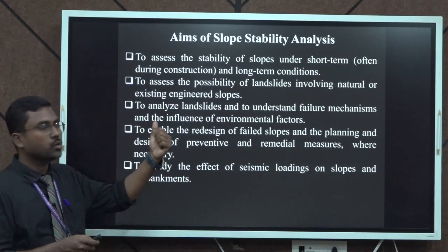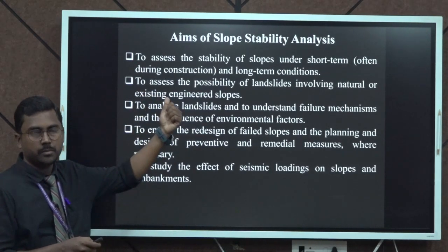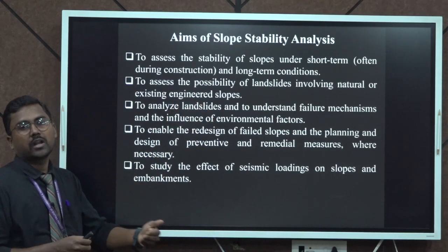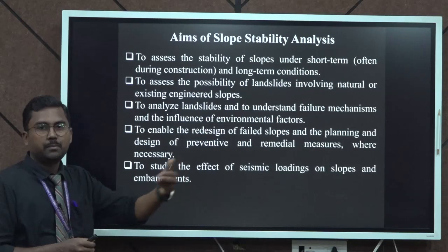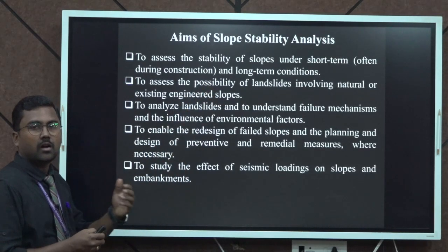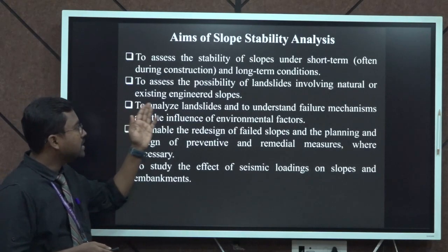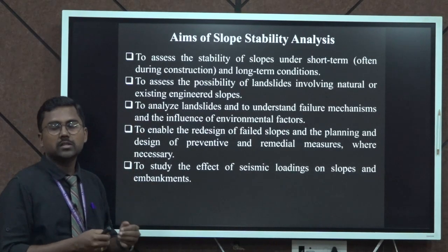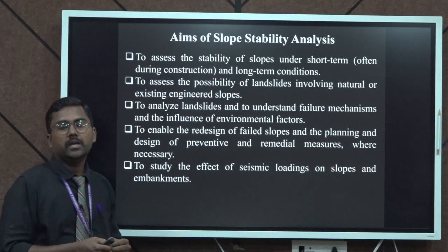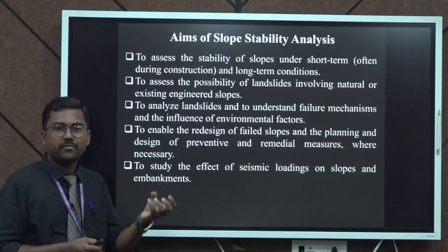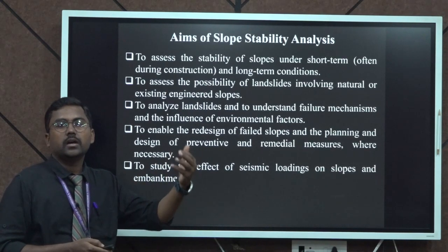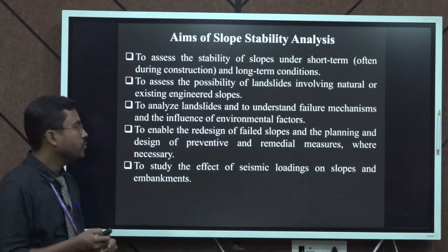The short term forces include the forces created during construction practice, and long term forces will be due to natural calamities or any creep load which is acting on the slopes, which will cause a long term effect. And to assess the possibility of landslide: whether any landslide may occur on that slope, in future as well, will be identified by making the slope analysis.